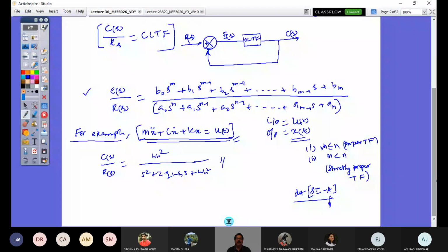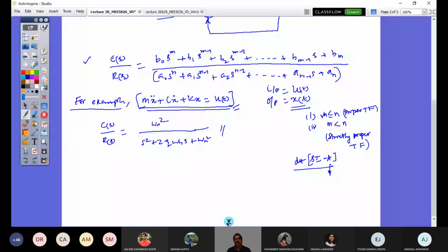How do I get this transfer function? That's what I'll explain with this simple, well-known second order system of a vibrating system. So what is this equation? Physically, how do you represent it? It can be represented by a spring and dashpot with the mass. This is K and this is C, and your forcing function is F of t here. If I draw this upside down, then an entire vehicle mass is just kept on this, so all the suspension I can neglect.